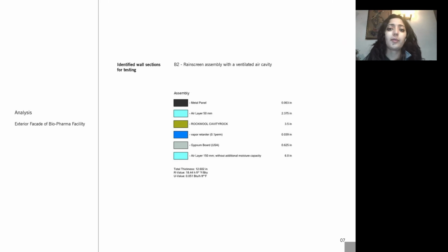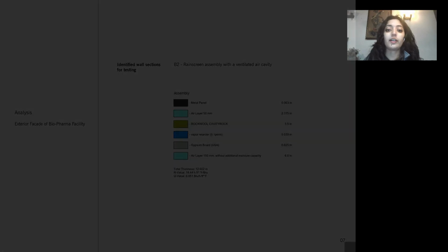So the idea came about: what if we ventilated the cavity with air at the same temperature as the mechanical space above? The airspace will never become cold enough to reach the new dew point temperature. Then, the ventilated cavity solution was also tested in all different joint conditions around the cold room to make sure that this was effective.